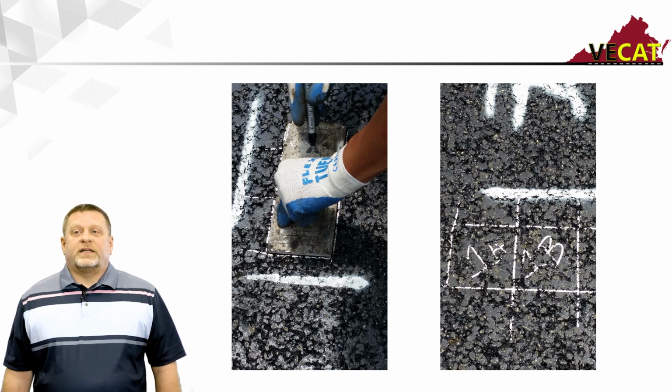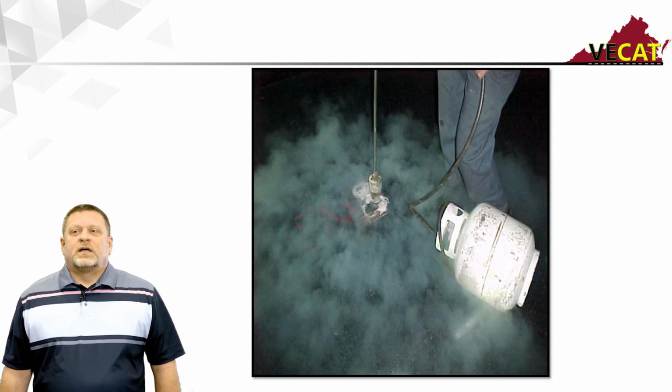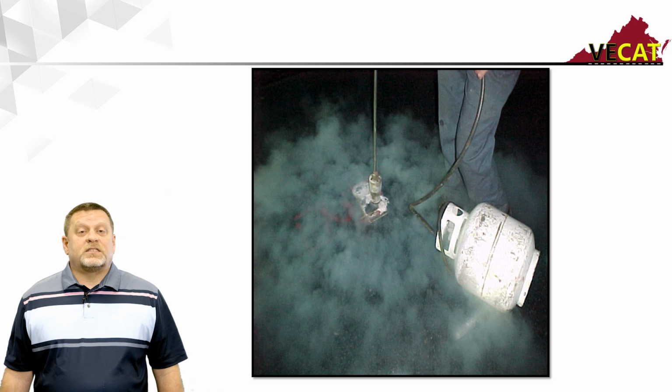Here, the technicians, there's a picture of the template for marking a plug location. You can see the picture on the left, he's marking it out with a marker. Picture on the right, he's already labeled 1A and 1B before he actually starts cutting. And if you look at this mix, you can probably recognize that we're actually doing this testing on an SMA mix. Before we do any testing, it's important that the mix is still warm, the mat's still hot.